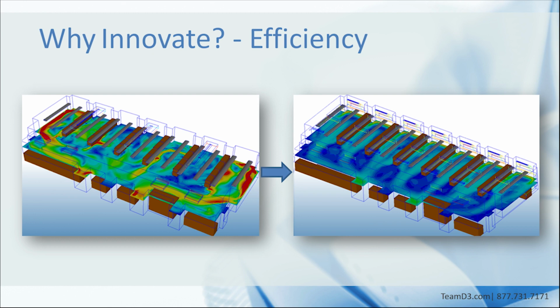Often, efforts to correct non-optimized flow will fix one problem but create another. We've all experienced rooms that are too hot or too cold because controls are monitoring another area with completely different thermal loads. Non-optimized flow not only creates poor air quality, but often cooling and heating equipment is consuming unnecessarily high energy to try and mitigate the problems in the design. Correctly optimized airflow helps designers size equipment correctly, place inlets and outlets correctly, and design efficient zoning and controls.